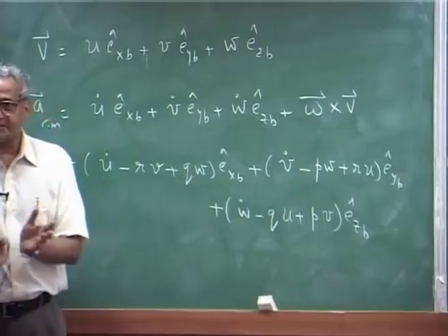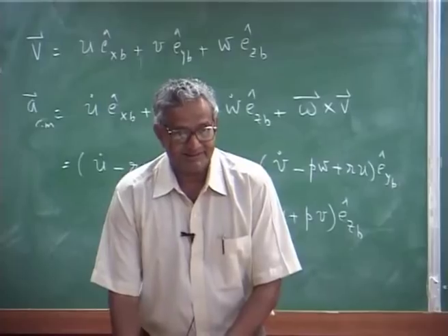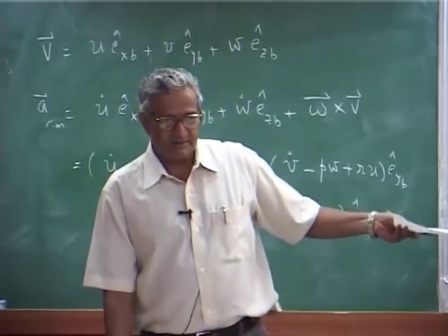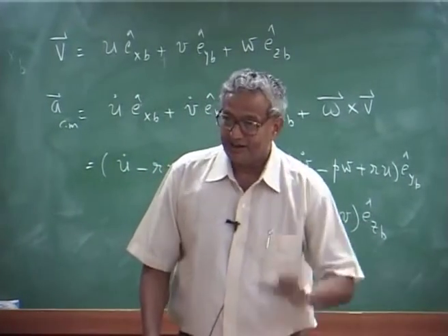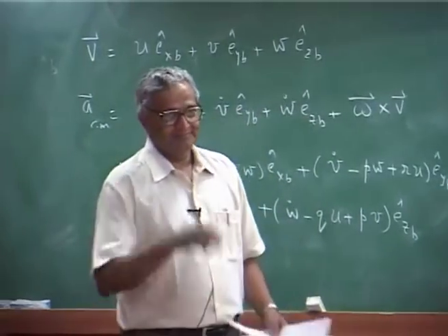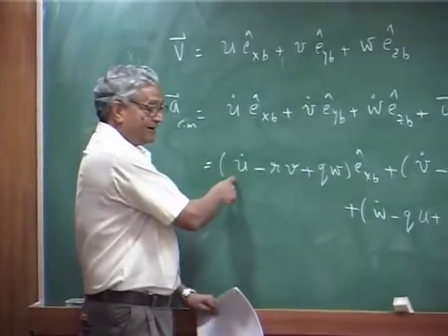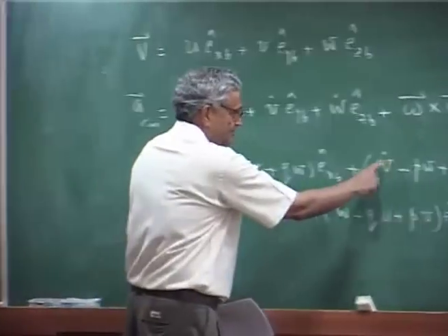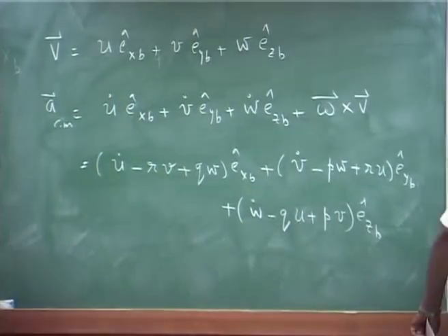So, what are the loads that act on the helicopter? You have main rotor load, tail rotor load, fuselage aerodynamics, and then any external bodies, aerodynamic surfaces, then gravity, all. So, what you do is you take all the loads and transfer them to the CG. You will write Fx equals mass of the helicopter times this. Fy is mass of the helicopter times this, Fz is this. That means you have 3 force equations.